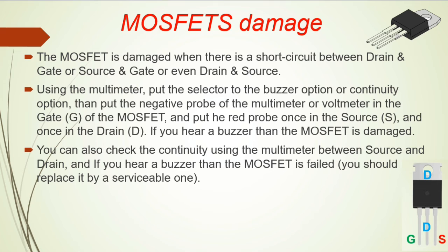Okay, there is another method to check if the MOSFET is good or not using just your finger. If you touch the MOSFET over here on its body and you feel that it is very hot, okay? Its temperature is not normal. That means the MOSFET is damaged, okay?